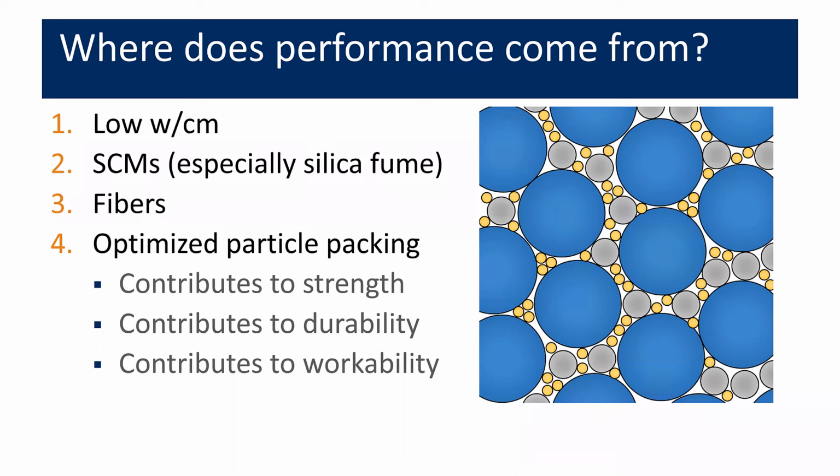We're talking about making the material as dense as possible, and so we need to be able to fit particles together from all different size ranges, with the fine aggregates being some of the coarsest materials in the system, all the way down to silica fume being the smallest material in the system. When you have that dense packing that comes from this optimized gradation of particles, not only do you get high strength and high durability, but surprisingly, you also get high workability.